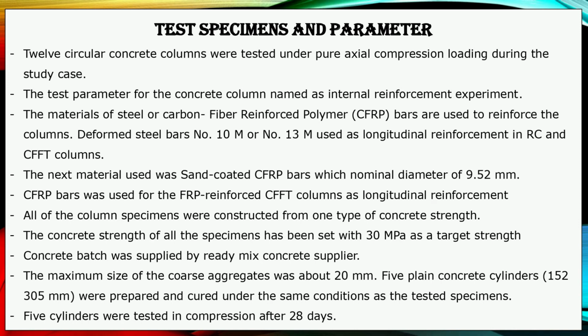All of the column specimens in this study were constructed from one type of concrete strength. The concrete strength of all the specimens has been set with 30 MPa as its target strength. Concrete batch was supplied by a ready-mix concrete supplier. The maximum size of the coarse aggregates was about 20 mm.